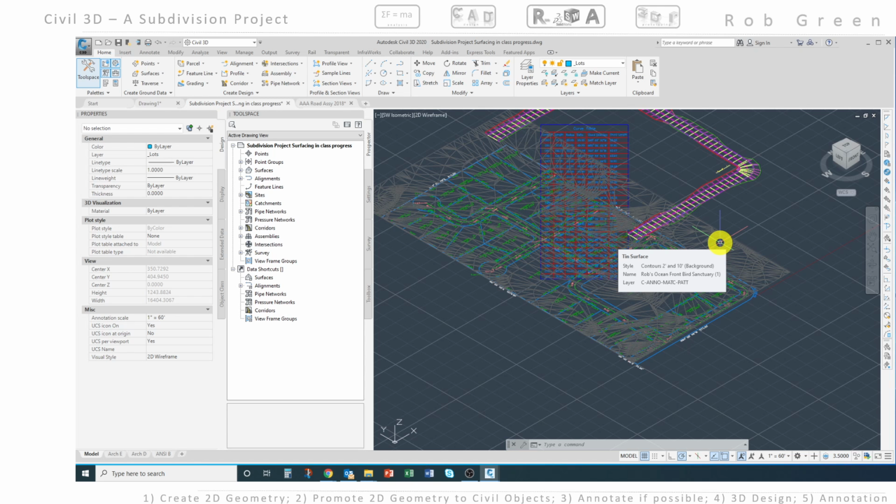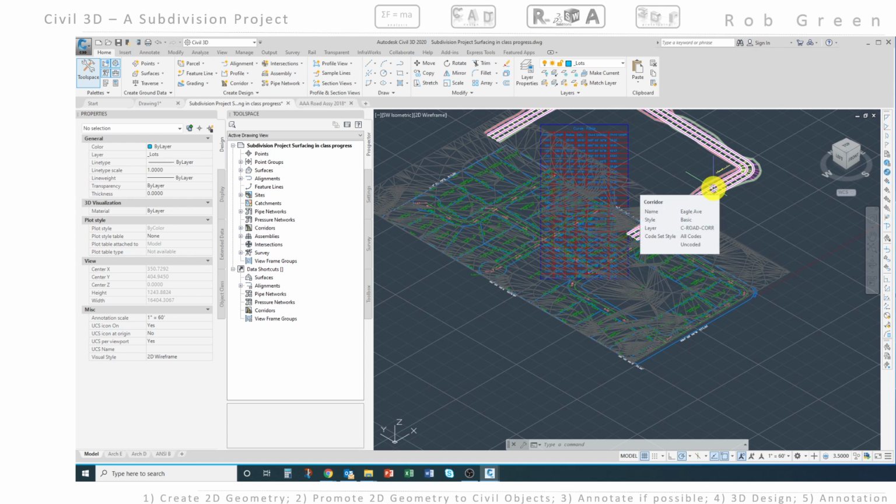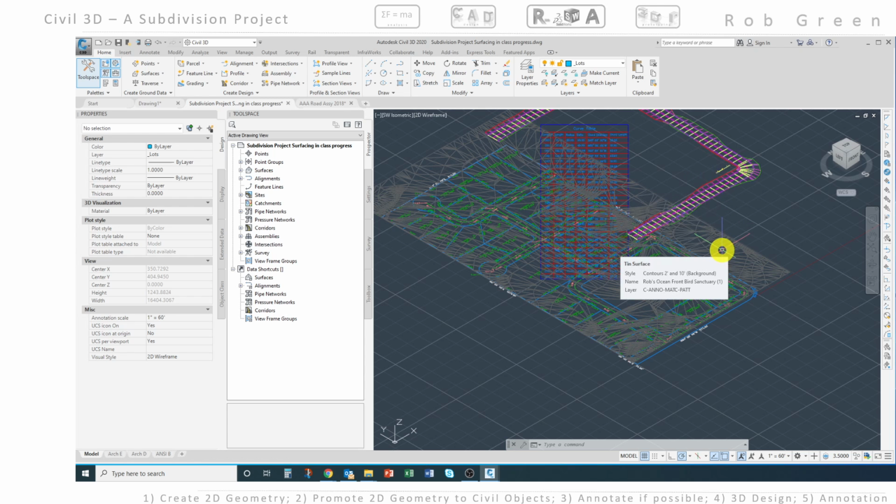What I will do is close out this session, and then in the next session we will fix that small lurking error, and then we're going to need to create a surface based on this corridor. And then we're going to create another surface, or actually I'm going to call it a volume, which is telling Civil to calculate what's between this surface and the existing land surface. Okay, hope this is helpful, and we'll see you in the next section.